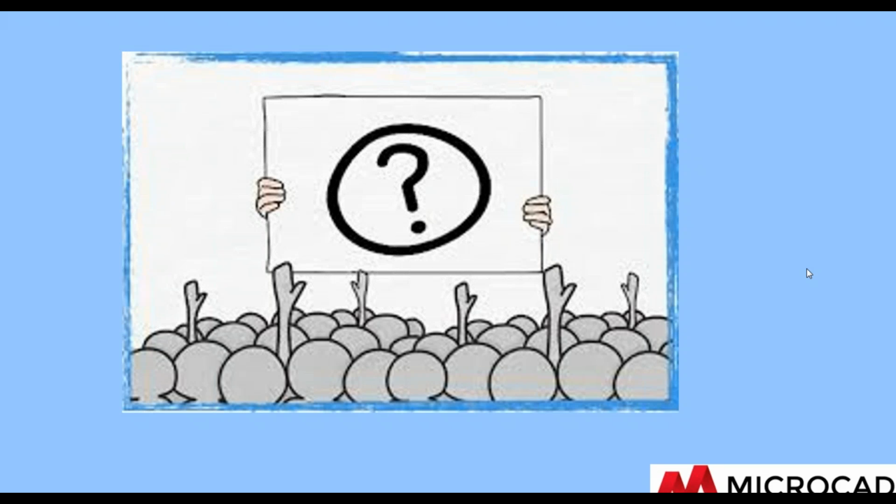So Sam as himself could have a certain level of permissions, but Sam could be a member of the architectural design team and as such has permissions based on that team assignment. Or you can assign permissions by companies. So if Sam is a member of XYZ Architects, then the company XYZ Architects could be assigned permissions. That makes it very flexible on how you can handle assignments.